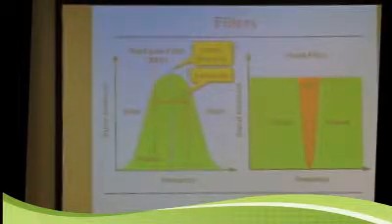Well, that's what a notch filter does. It stops one little signal, it passes everything else. So in this particular case, it would pass, say, 3 kilohertz or better, which is your single sideband signal. But if you have a CW signal that's 500 hertz wide, you can notch that out. And essentially, again, none of this works perfectly. It's not going to totally remove that signal, but it will make it so weak that it's not so invasive to you. It doesn't cause you to cease to be able to communicate with the person you're talking with. So that's why you have such a thing as a notch filter.